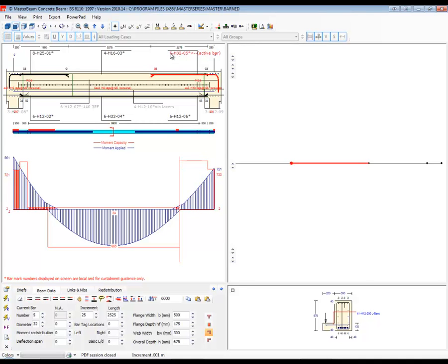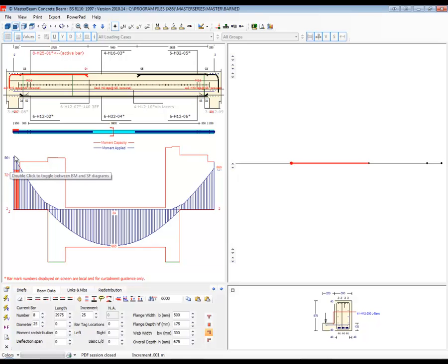But if we went up to say 32s, and likewise here, I can drag that bar across. We're beginning to get our solution. And obviously over here, we might need to drag this bar considerably further over, and we just have a little problem there. And remember, we can distribute the forces, which causes me a problem down here. So oops, pull that back up. So the configuration of the section is not right. It's going to be too congested. We need a bigger section.